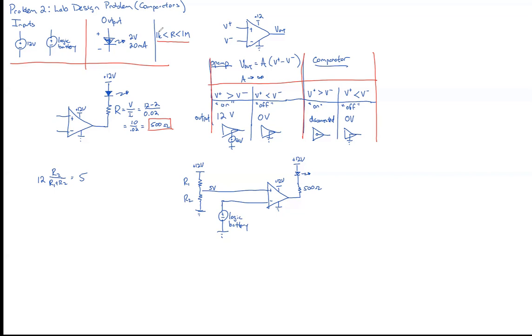Now, the grind-the-crank way of doing it is to ask yourself: you can see that there's going to be some current that shoots through here, in this direction. And that's always going to be shooting through. No current ever goes into the comparator. So this current's just wasted. And it's not unreasonable to say you'd like to minimize that amount of current. But if the current's too small, you'll run afoul of the resistors getting to be too big over here. So you might say, let's just keep this current to something small.